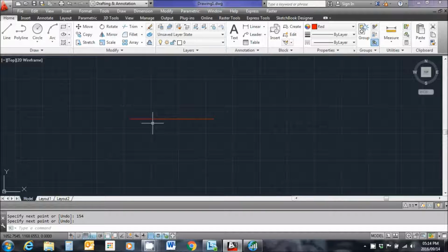Okay, so the total vertical change in height between manhole B1 and manhole A6 is 7 meters. So I'm going to allow an additional 3 meters to give me some depth on my long section for the sewer alignment, so that's a total drop of 10 meters. Now, because the sewer line started at a level of 90 and I'm going to take 10 meters away, that means my datum will be at a level of 80 meters.